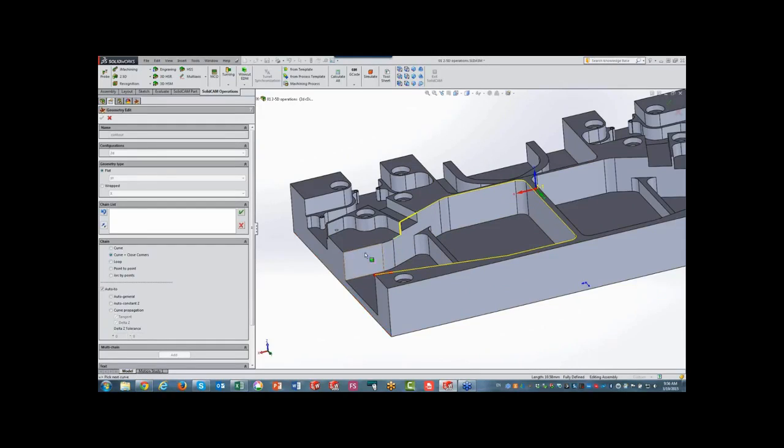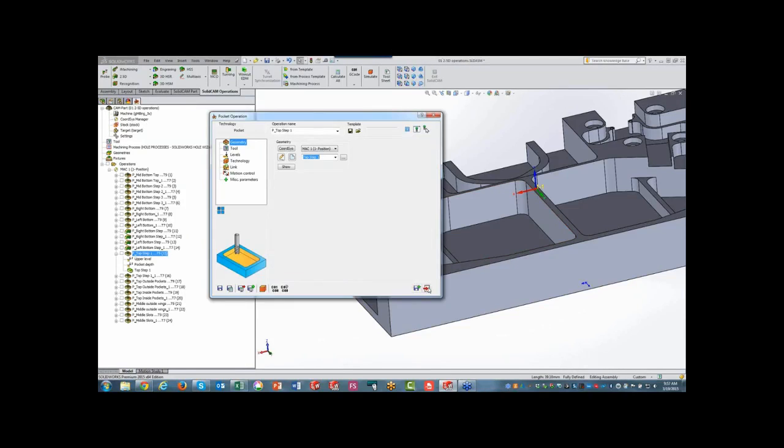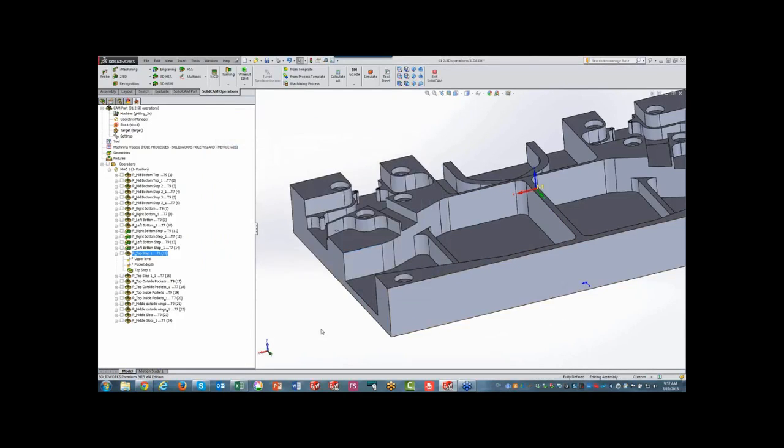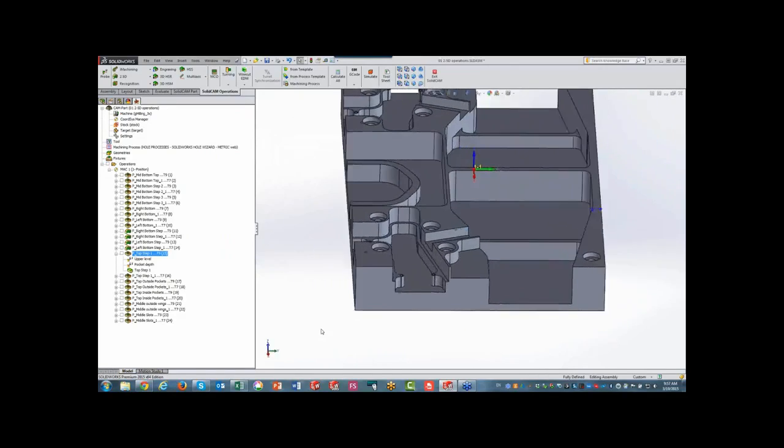And then I'll just click on this curve, and I'll just accept this the way it is right now, and then it'll mark my open edge as shown over here. So you see, creating a geometry over here is not always straightforward. Okay, I'm not going to accept it because I already have my geometry here. I just wanted to show you what's involved sometimes when creating chain geometries.